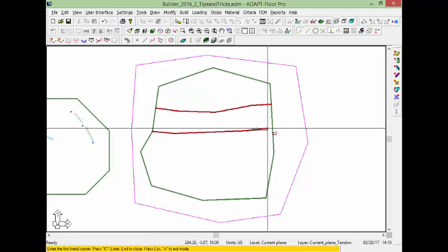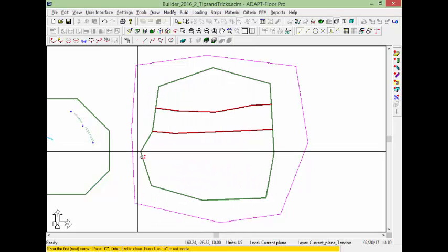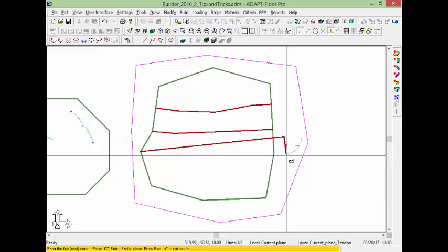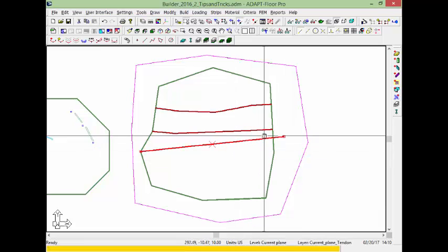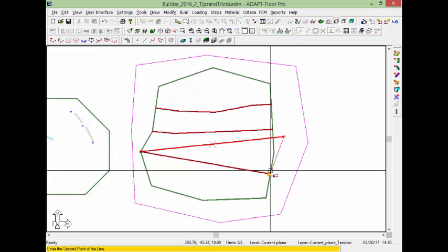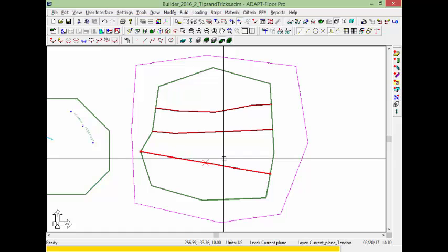This also works when we're in modeling mode. So we'll go ahead and press enter, and again, if I, for example, overshoot this outside of the slab, press enter to close, and then I go back and readjust the tendon, I can either select this perpendicular edge or even this perpendicular edge to realign that line.